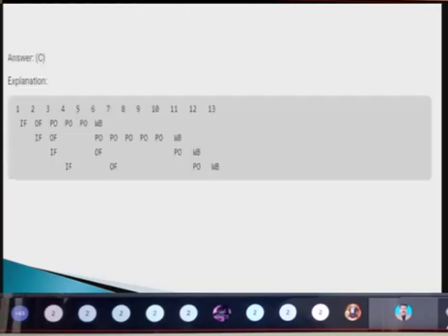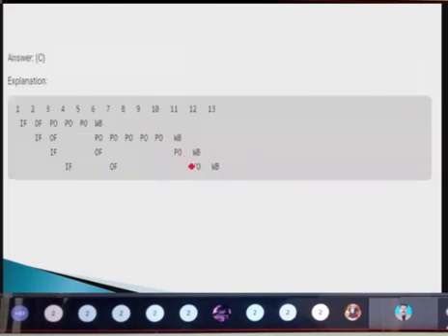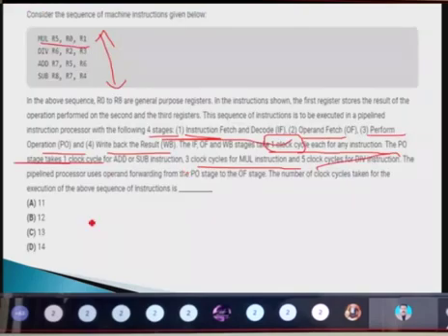And then again for subtraction, the 4th one, instruction fetch, again I'm just doing this operand fetch, and then it is actually subtraction now, so I need to wait till write back of previous instructions. So perform operation, that is 1 clock cycle, and then write back. So totally 13 clock cycles I need. So I will be going with option 13.